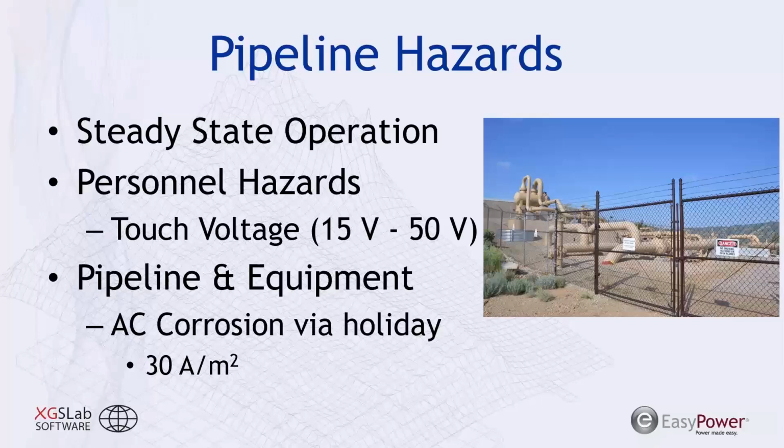There's also concerns about the pipeline integrity, and there's a corrosion known as AC corrosion, and this is the phenomenon where you have an induced AC current on your pipeline, and that can lead to accelerated corrosion on that pipeline. Wherever that coating may have a small nick during installation, you can have significant AC voltage there that leads to much faster degradation of that pipe.